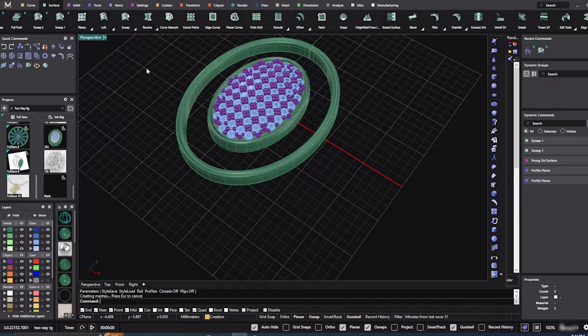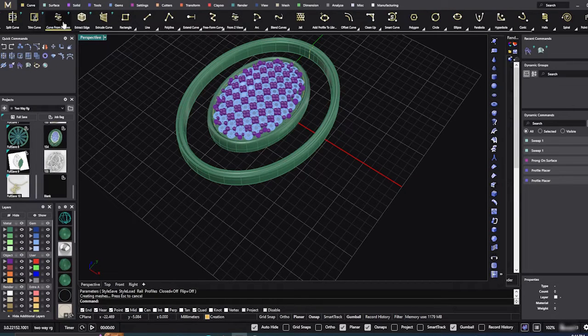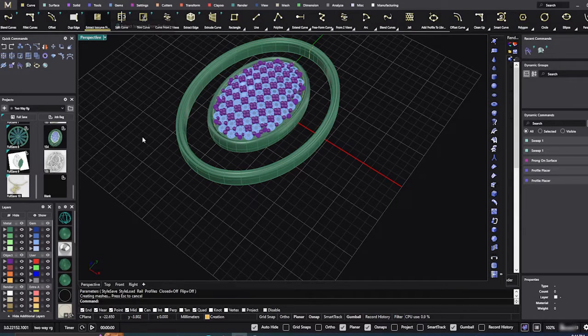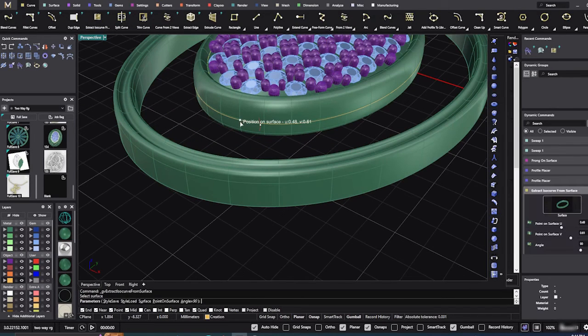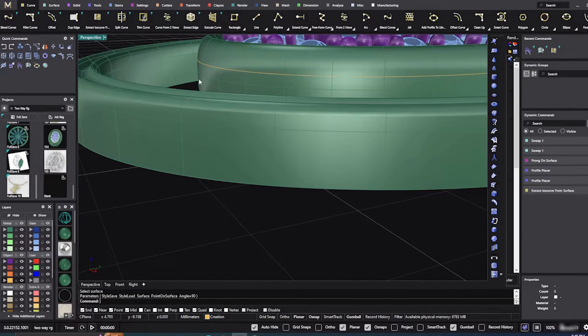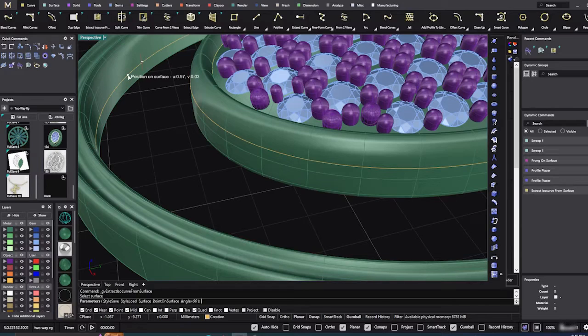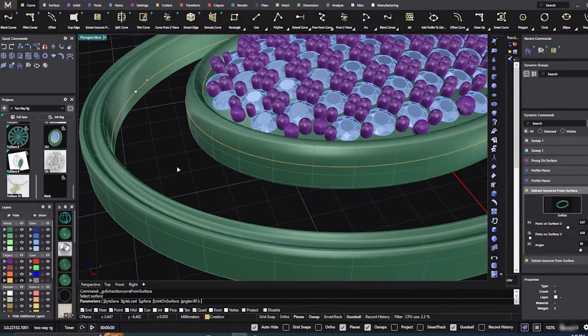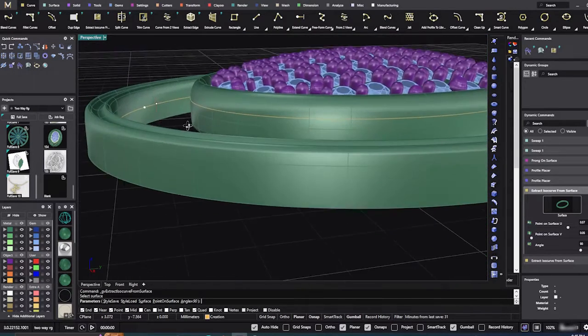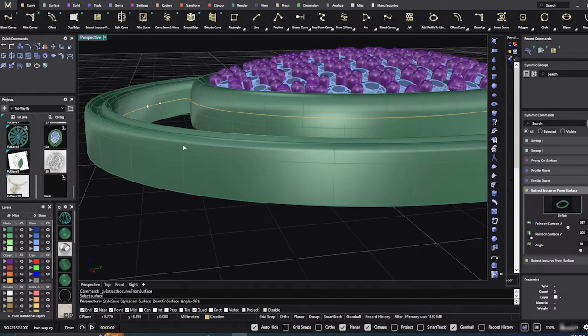And from here, what we're going to do is go to a curve, go to our ISO curve, so it's down here on the other end. ISO curve, and we're going to select an ISO curve from here, and I'm going to drag it up a little bit, yeah, maybe around there, hit enter. We can always move that, and then right click and click on this surface over here, reactivating the command, and click this point and drag it up a little, maybe a little bit. Yeah, that might be okay.